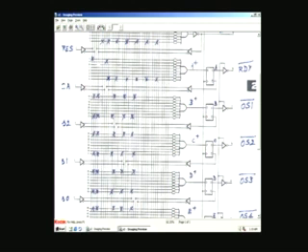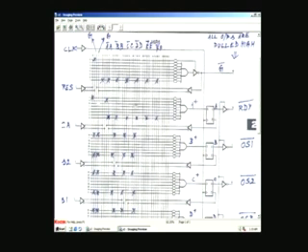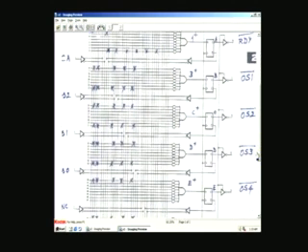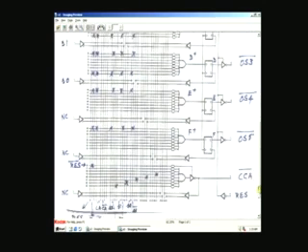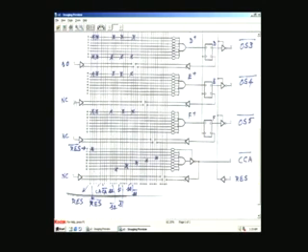bar, and the inputs are of course, as you have seen earlier, we have shown reset input which comes from that Schmitt trigger combination, the RC combination. The clock is given to the first pin, the S1, S2, S3 inputs and no connections. The other connections are not used. NC means no connections, we are not connected. NC, these three are not connected.